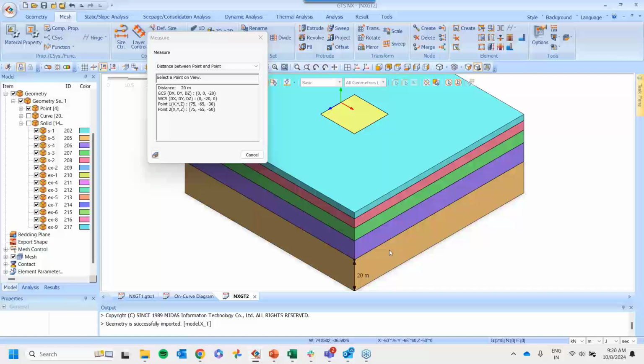Now, fractured schistose rocks are extremely weak. So they possess very low bearing capacity and sometimes they also need reinforcements. They come under the category of rock, and schists are one of the worst quality rocks which are available in nature.